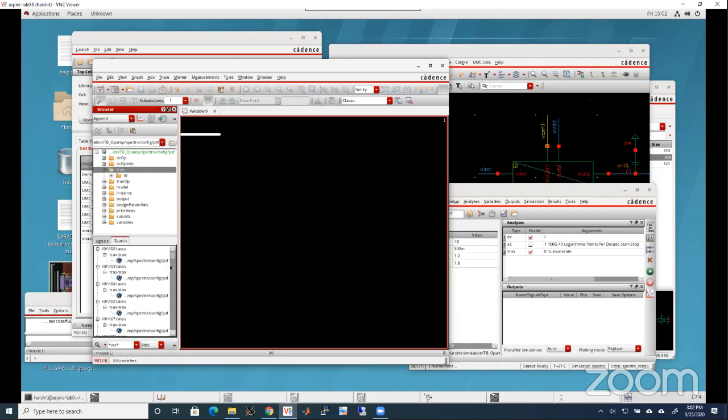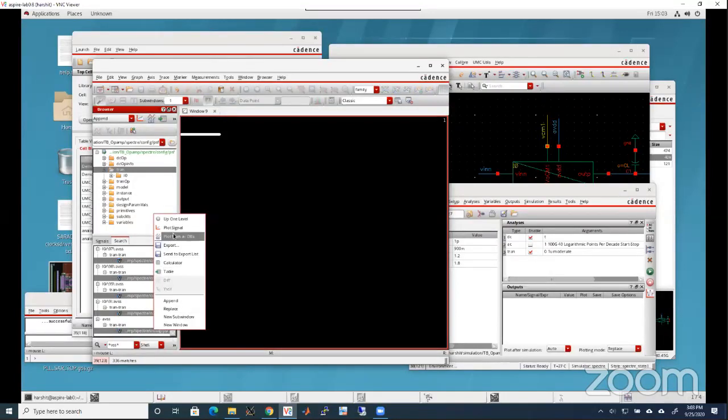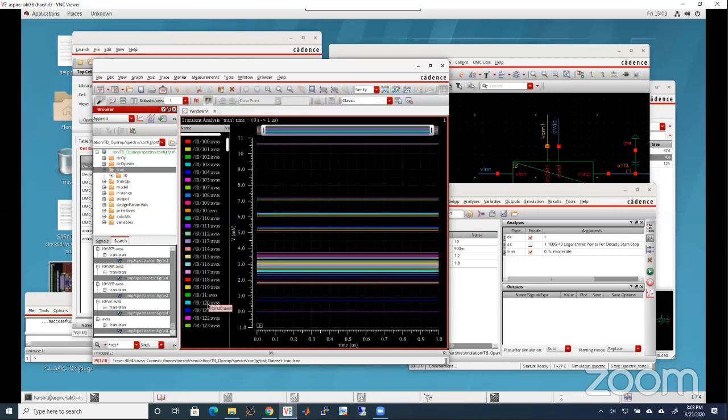Okay, so we will now look at how is the VSS. So you can see we gave only one VSS, but you can see that VSS gives you almost 11 millivolt drop, 10.6. Ideally, it should be 0, but I'm not getting this. So when you are doing this analog layout, 10 millivolts is a lot of drop actually. But for us, it was okay, because we made sure that it is 10 millivolt drop here and 5 millivolt drop there, on the top side VDD. So our circuit will effectively be getting 15 millivolts less than what it was supposed to get.